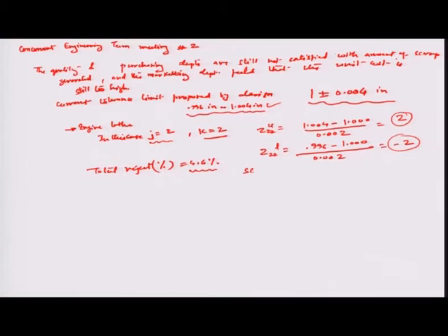With this on board, we can again calculate the scrap fraction to be 0.046, and similarly the number of units scrapped, y s 22, we call this 22 because j is 2 and k is 2 in this particular case, which is equal to the technological coefficient for the scrap times the overall output, which is 0.046 times 1000, approximately 46 components.